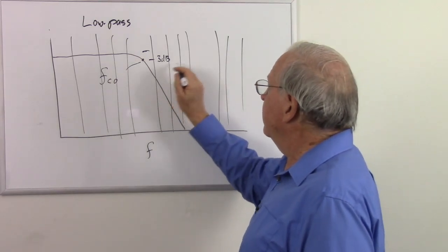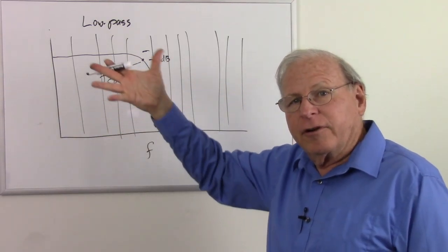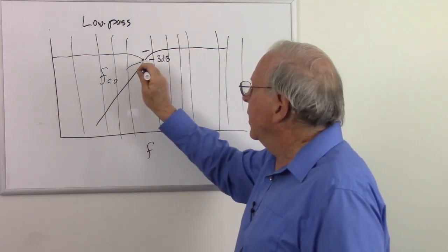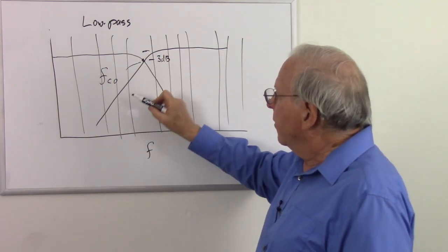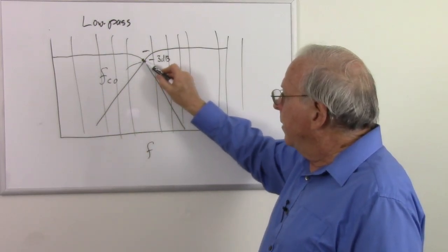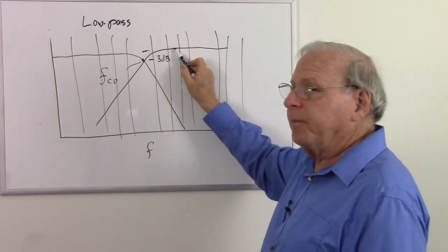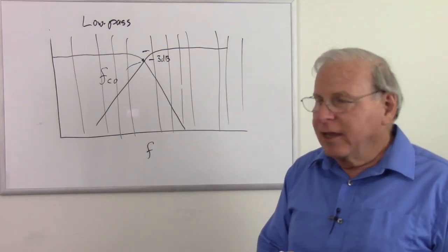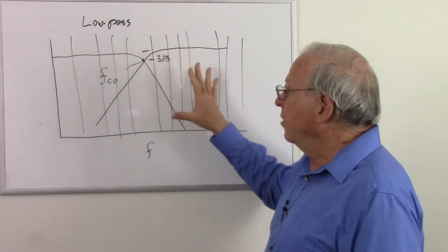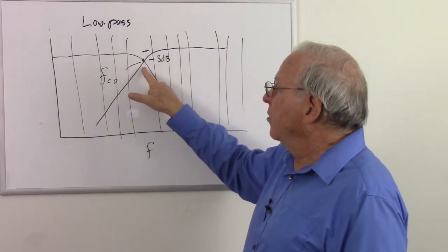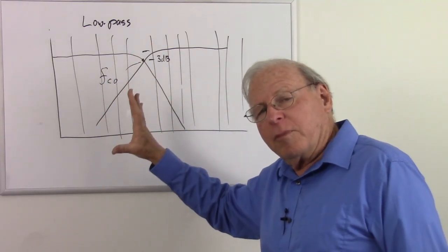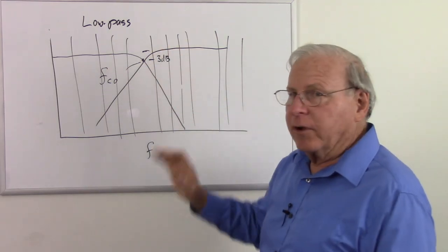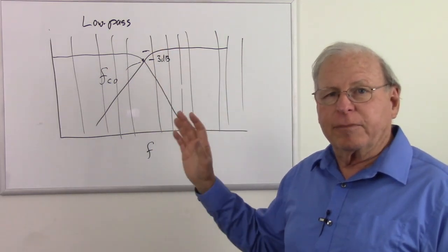Now if it's a high-pass filter, we just flip the capacitor and the resistor, and we're going to get something that looks more like that. And once again, the cutoff frequency is where the response comes up and up and up, and when we are 3 dB below the peak, we are at the half power point, and that is the cutoff frequency again. So that's how we define the parameters of an RC filter. The cutoff frequency is where the voltage across the component that's making the output is 3 dB below the max, and whether it's a low-pass filter or a high-pass filter is simply the orientation.